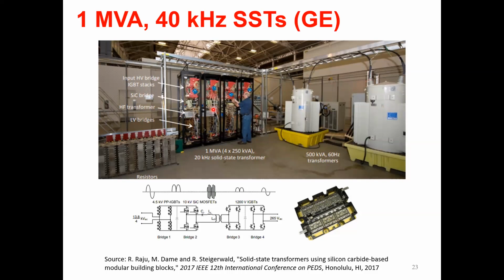Why is that so? Because since they were trying to operate at very high switching frequencies and high voltages, there were a lot of issues and fault handling capabilities which were needed to take care of all the power electronics here. So a lot of these are relays and breakers and all those, because you don't want your power electronics to break up. So even though the high frequency transformers themselves were very small, the solid state devices and the protection, the cooling, everything added together, the system actually became much larger.